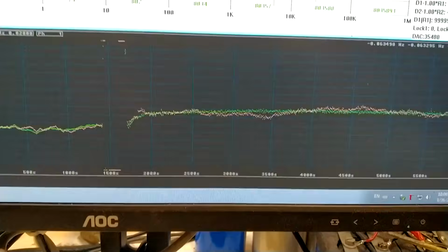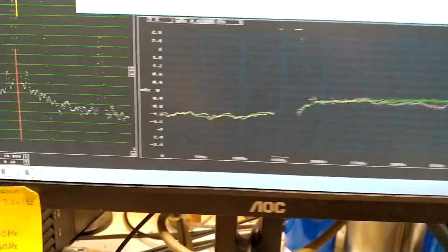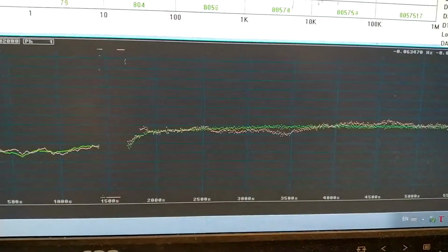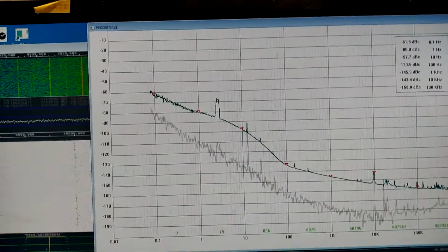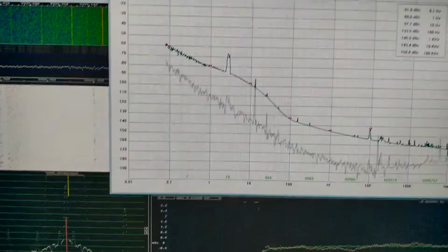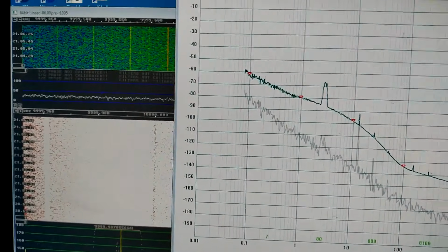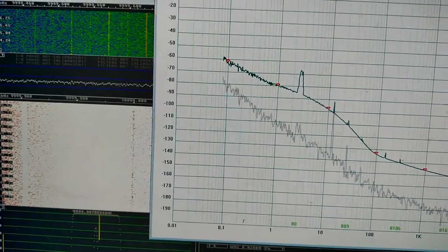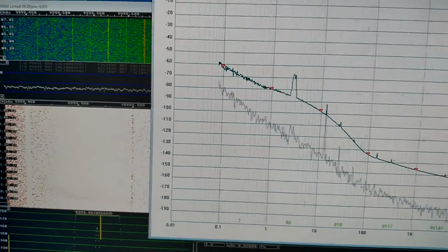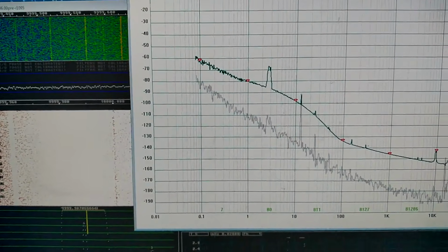And it is clear that the instability of the channel 2 oscillator is similar to what I have seen here, but it's more difficult to see it since the track is so wide. And when looking with the PN2060, it doesn't look very interesting. At 0.1 Hz, the noise is minus 62 dBc per Hertz. So one has to go much closer to the carrier to see the merits of the rubidium source.